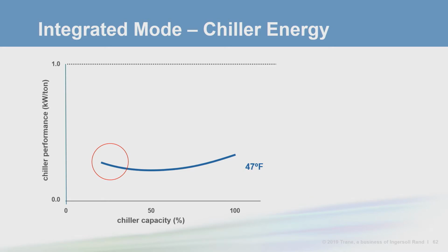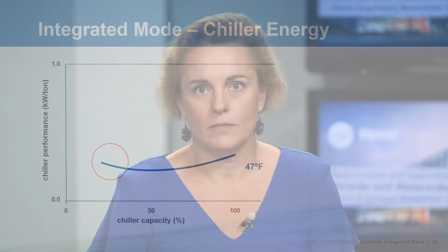Said a different way, when a chiller is running, there is a minimum kW that it needs, regardless of load: the controls, any ancillary power use, and the minimum compressor energy. When loads go down, even the best performing cold weather chillers have worse efficiency than might be hoped for. One suggestion is to give the chiller more load and the Waterside Economizer device less. This is difficult to do in a series arrangement, but it can be done. It's easier to do in parallel Waterside Economizer arrangements.